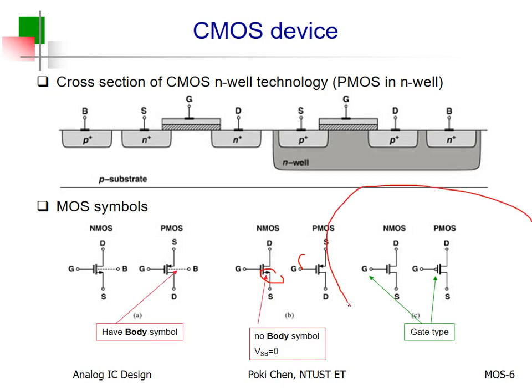So they can enjoy this. You can say NMOS and PMOS are exactly the same, except for a bubble. Again, bubble means not. It means the polarity of the voltage applied to the gate needs to be reversed. Again, high for on, low for off. But here, according to the bubble, low for on, high for off.